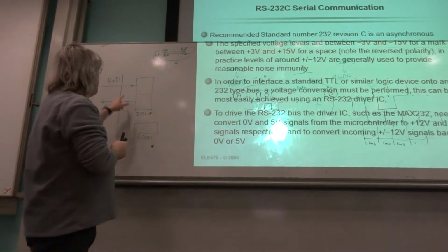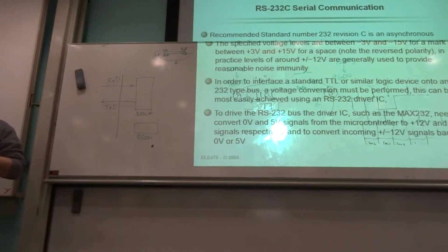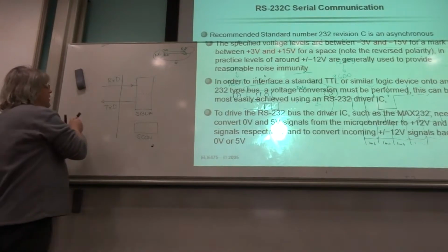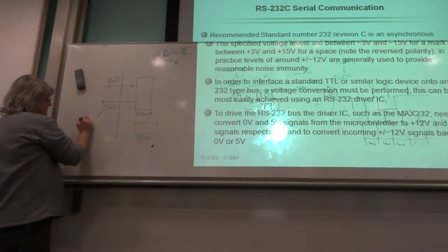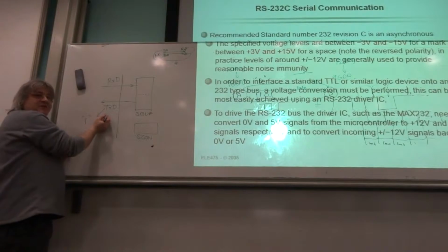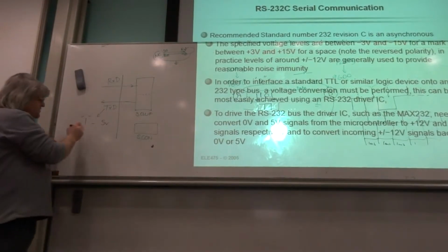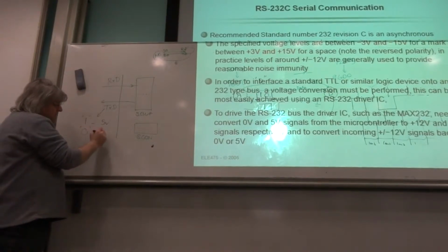What else do I want to say about that? Now, a lot of computer systems, now we're saying logic 1 on the transmit interface, if it's TTL compatible, logic 1 means a voltage of about 5 volts. Logic 0 we represent by about 0 volts.